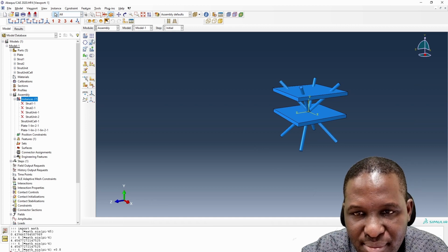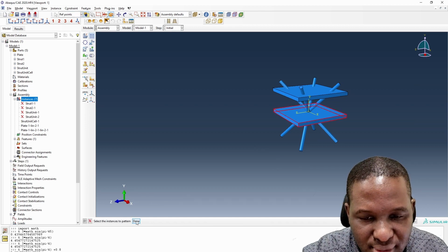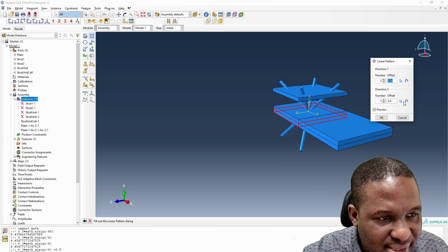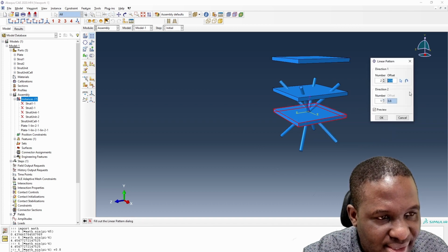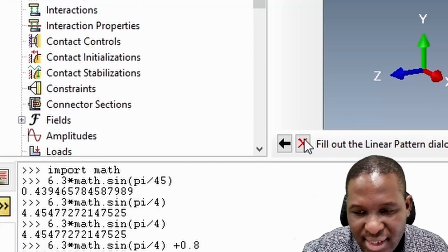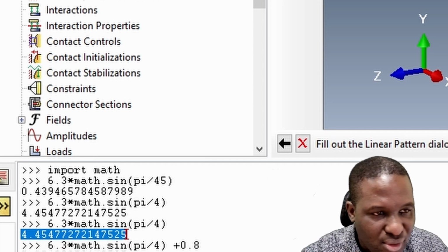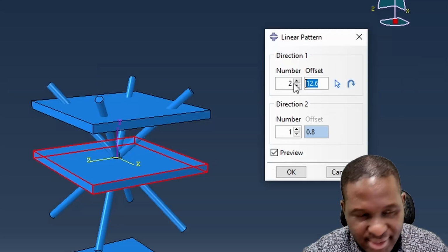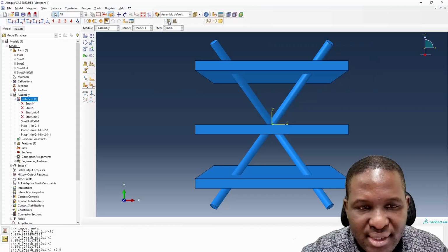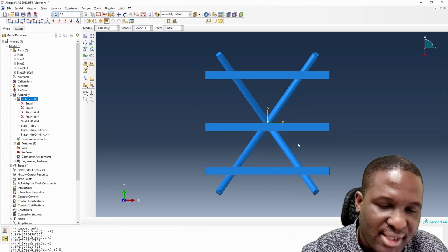So we do the same linear pattern of this middle one, okay. So we start again, we don't want this axis, so we want it oriented in the y-axis, and we flip it around. But the height we just need is this 45 because the base is no longer included in the calculation, the base height. So we've got that. Everything looks symmetric and it's fine.